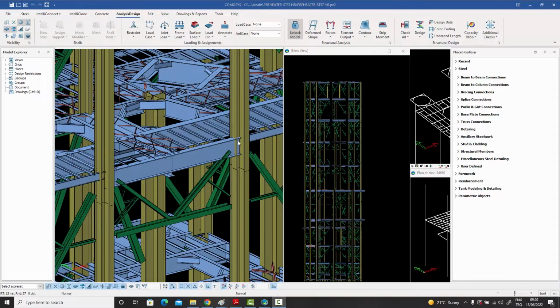And this is normal practice also, because especially in seismically active areas, your structure is going to be pushed to the limits, and you want your moment resisting connections to be designed according to capacity rather than load. They're actually going to touch the plastic capacity in seismically active areas. But as far as the floor beams are concerned, almost 99% of the times, they're a different story.